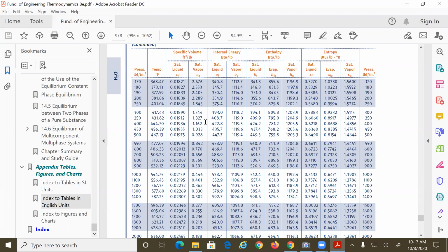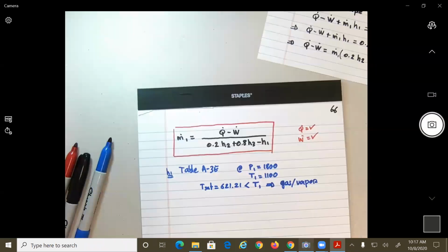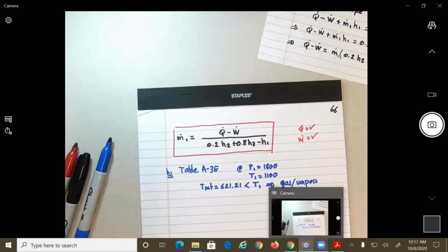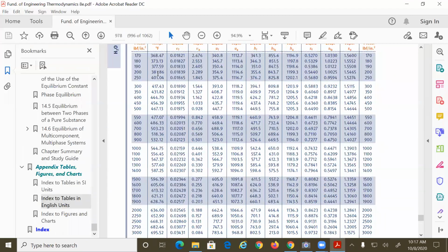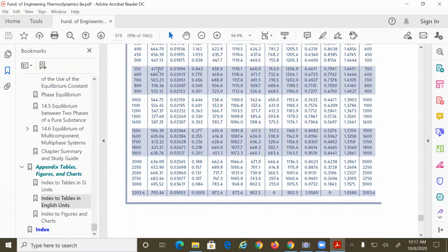which is lower than T1, so basically what I'm saying is that since this is lower than T1, this means we are on the right hand side of the curve, no? So we are on the steam. Did I close that figure already? Yeah, already closed it off. Okay, so that means that we need to go to which tables? We need to go to the tables of superheated, no? Which are the table A4.